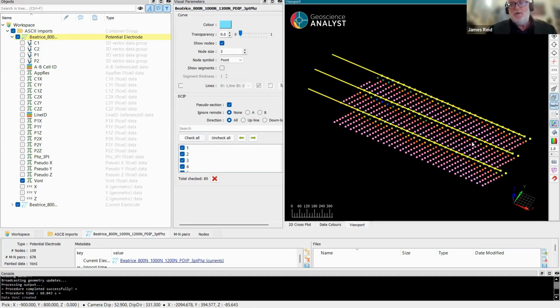The next thing I'm going to do is bring in a DEM, and this is some of the pre-processing I did. This survey is obviously in local coordinates. You probably saw that in the preview of the ASCII file. So I have also rotated the DEM, which was in UTMs, into the local coordinate system. I've just done that ahead of time to save a bit of time.